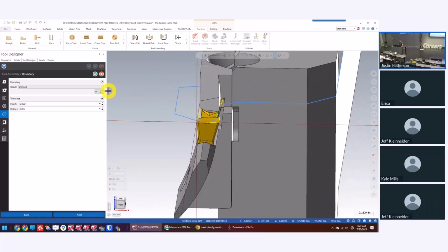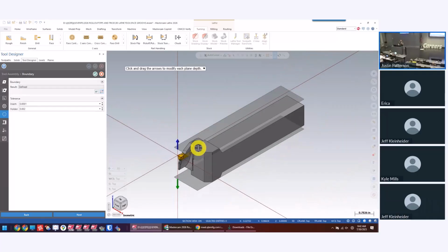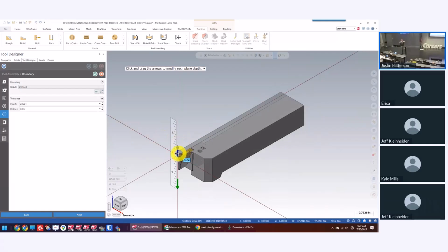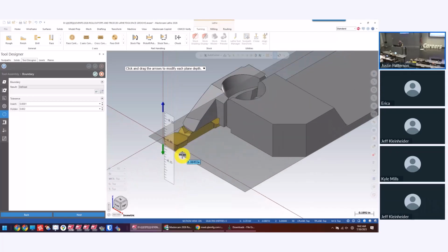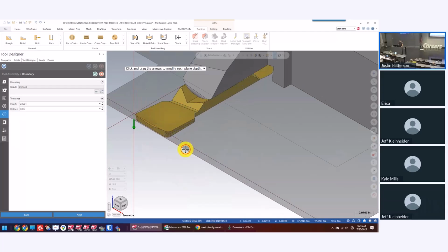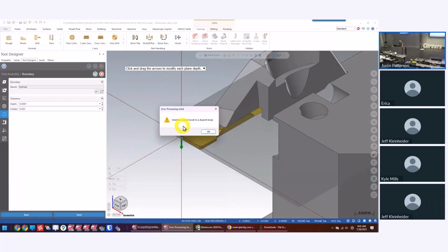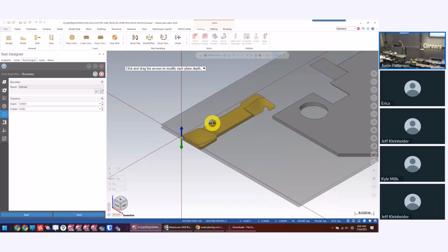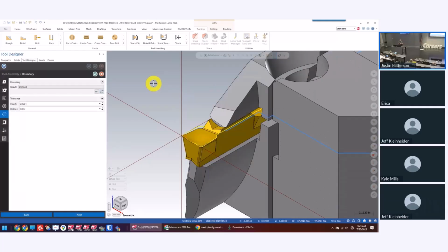So I want to come in here and go to change the boundary. I can just tell it, hey, let's only look inside of this. But I will say, you have to be very careful. If there's a point where you trim and it leaves a solid detached, it'll alarm out on you. It won't let you do it. So just be very mindful of that. But yeah, I'm just going to come up here and bring it up almost to the tangency of my radius, because I'm really not too concerned. Okay, and then I'm going to bring this down about right there. See, right there, disjoint body, because it left a little. So you can make it work, but really going right there is perfectly fine. And you hit enter, and now you get a new boundary profile that's allowing it to cut, okay? So there's that.